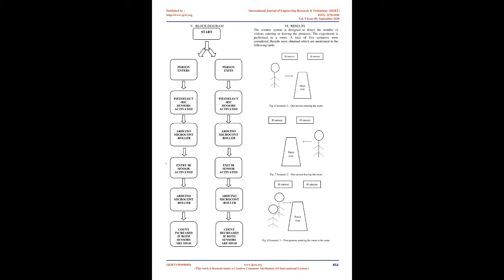Power. All Arduino boards require a power source to run on. There are two ways to power the board. The first is by using a USB cable connected to a computer. Alternatively, the board can be powered by connecting it directly to a wall power supply using the barrel jack given. But the voltage of the power source should be in the range of 6-12 V.